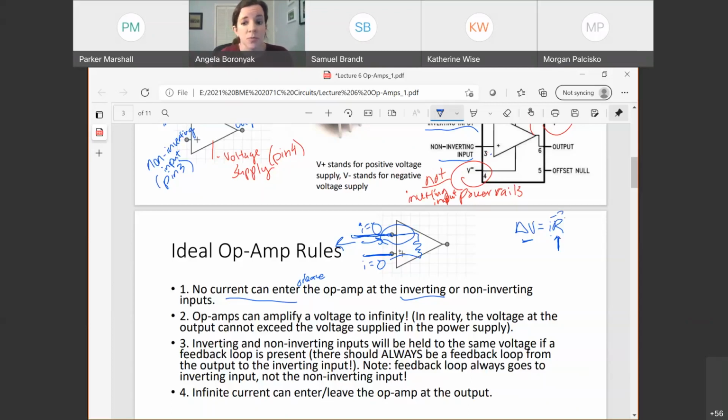Yeah, then it becomes really small. So if you make that resistor impractically large, normally we're talking about hundreds of mega ohms, 10 to the 6 ohms, then practically this current is going to be so small that it's practically zero. And we like to assume it's actually zero. In real life, it may not really be that, but it's going to be really small.